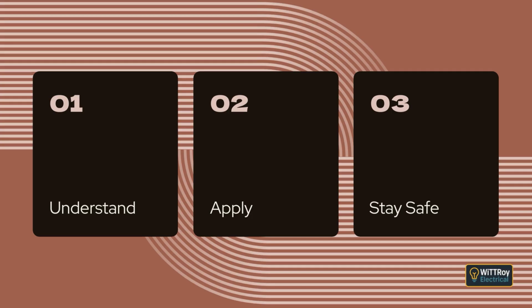The notes explain that a harmonic load above 40% of the single-phase load is regarded as substantial, and that information about harmonic currents can be found in other standards. There are also exceptions describing situations where out-of-balance currents or protected neutral arrangements allow the neutral to be sized differently, provided the neutral cannot exceed the protective capacity of the circuit.